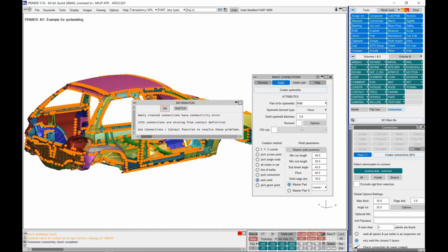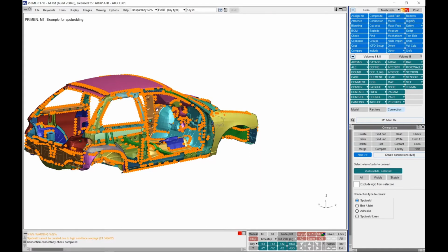So the spot welds we've created are mesh independent. In order to basically make them have the stick in effect of a contact connection, you need to define a tied contact, and this is just a reminder that at the moment you've just generated the actual FE, but you need to create a contact, and I'll cover that shortly.